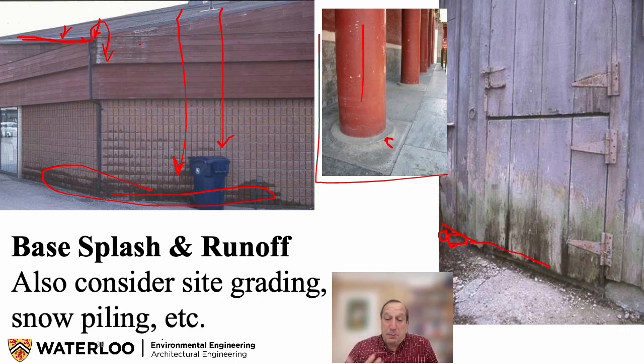It's in the building code, in Part 9, that specifically says you have to keep your cladding a minimum of 6 inches or 150 millimeters above grade. This is just an example of why. It's a good rule of thumb to protect most claddings from damage from water that's at the surface or splashing or melt water, which will, of course, over time degrade most systems.